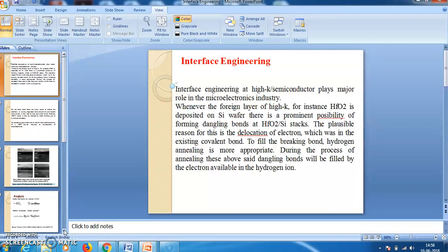Depletion is a direct indication of the interface of the oxide and semiconductor. If the interface is severely struggling with so many defects like interface trap densities, this depletion may get stretched, or some bumps and kinks may appear on the depletion region.